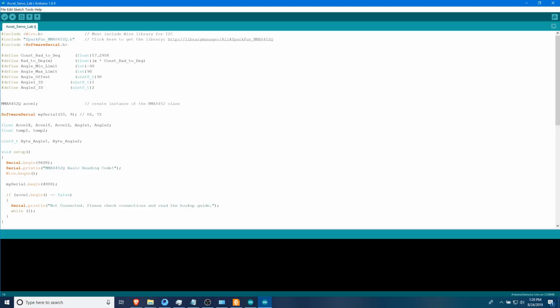That is very handy when you are converting a float into integer, because without the typecasting you might get some overflow and incorrect results, and it's just bad practice to have that. So for example, if I have a float tmp1 and an integer tmp2, and I'm doing something like tmp2 equal to tmp1 times something like 567, in this case I should be typecasting everything.